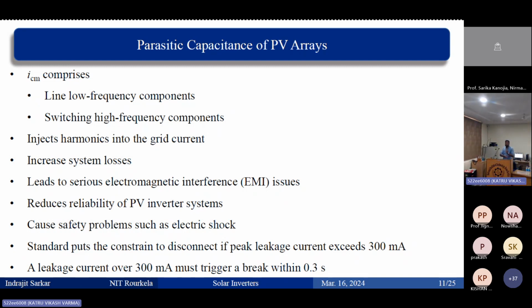So grid current is supposed to be a pure sine wave. The problem is that nowadays, if you go and see this socket that you have here in the DSO, it's a little bit flat on the top. That gives rise to third harmonic voltage component. We analyzed this once during my PhD studies.